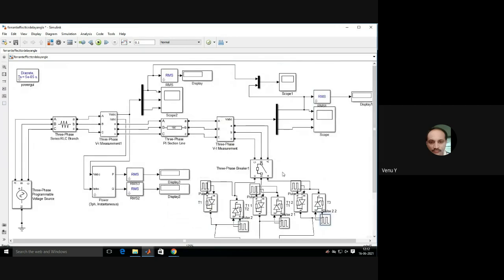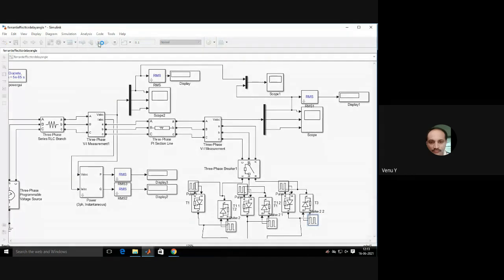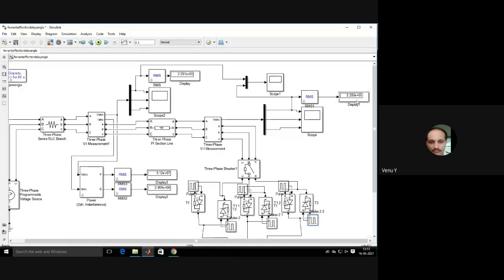And this breaker is initially open. At first cycle it is closed and it is open after 5000 cycles. So you got 229 kV sending end voltage, 228.5 kV receiving end. Still you can tune this. So for minute changes, you need to go for closed loop control.